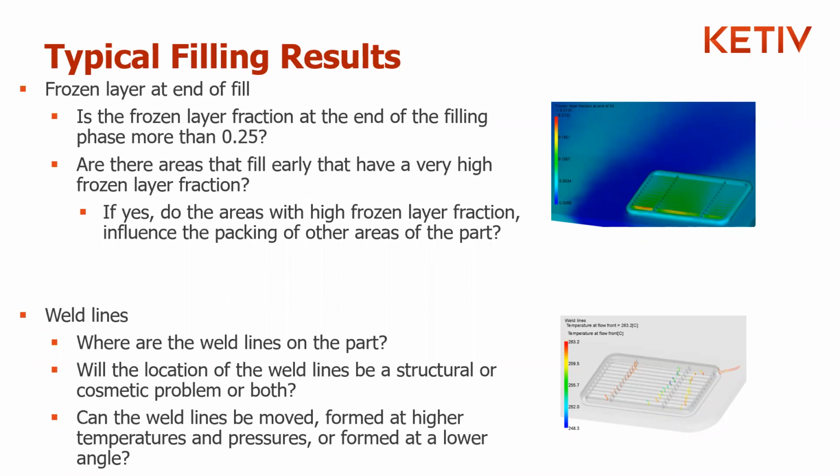Weld lines, again, there are certain areas where you do expect to see weld lines, of course. In this case, on that particular cover, as you can see there, every kind of gap, every discontinuity in the geometry is likely to cause some kind of weld line. If that shows up in the middle of the part, or in an area where the part's going to be most stressed, then maybe that's not the best approach to molding that particular part. Maybe there needs to be a different approach. You may have to go back to the drawing board for that, but you have that information beforehand, and that's the big takeaway.